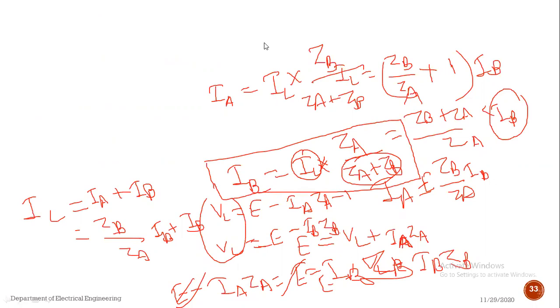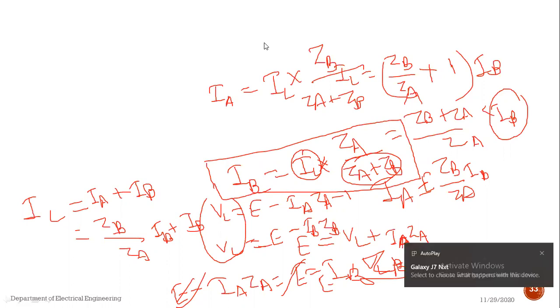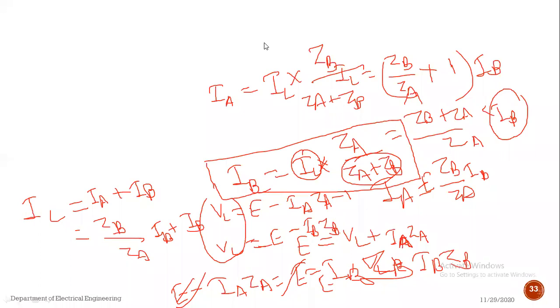So this is the simple derivation to calculate the load sharing by each transformer. प्रत्येक ट्रान्सफॉर्मरचं लोड शेअरिंग कॅल्क्युलेट करण्यासाठी this one is one of the simple derivations. Okay, that is load share by each transformer, IA, load shared by each transformer is equal to load current into opposite transformer impedance divided by sum of impedance of both the transformers. Similarly this equation is used to calculate the load of the other transformer. Other transformer चा load जर calculate करत असाल, we are able to calculate this load by using this formula. Okay, so this is the simple derivation.